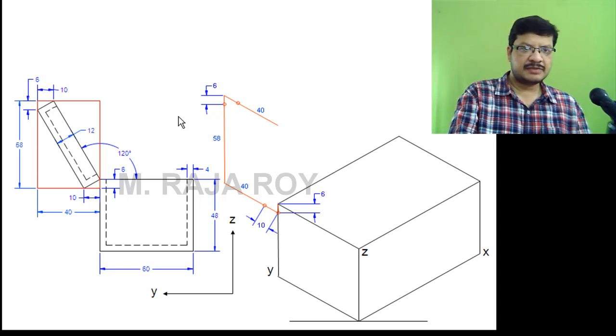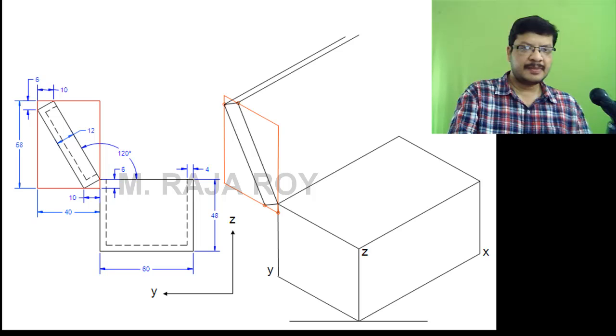Then put a point at a distance of 10 mm. This point. Now join like this. Now this parallelogram is ready. Now these endpoints are ready to draw these non-isometric lines. Now draw the non-isometric lines. And along these four corners, now you draw the 90 mm long lines and join it like this.